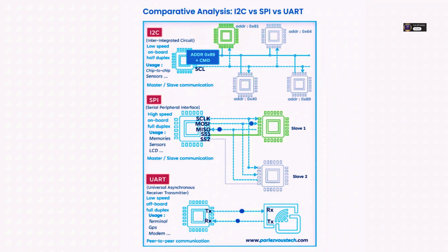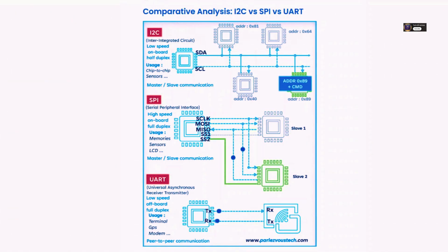I²C is a bit limited by its single bidirectional data line and those pull-up resistors we need to talk about, but critically, compared to UART, I²C is synchronous. It relies on that shared SCL clock line for timing. Right, the heartbeat. Exactly. Every data bit on SDA is timed by a pulse on SCL. Master and slave always know exactly when to sample or change the data.